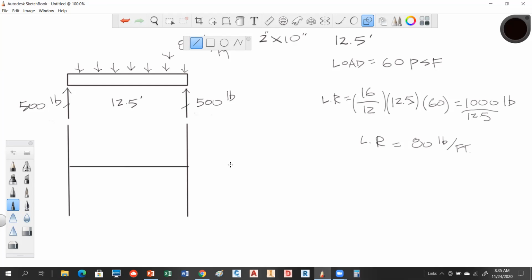So I'm going to put my zero axis line. So this is going to be my zero shear line. Now again, because we're not solving moment in there, we don't need a moment diagram, just the shear. Okay, so what's true about when we start out over here? What's happening? The shear is starting out here and it's going to what? 500, right? 500 pounds of shear at the reaction, correct? As you step across this beam, what's it doing? Staying constant or dropping?